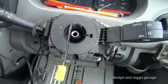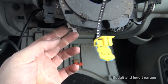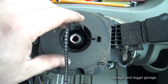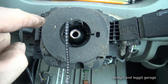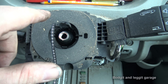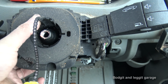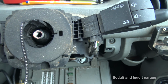Now, here is our clock spring, and on this one it's really handy, there's a lock. So you can actually wedge this up if you were to take it off, to stop it turning inside, because this has to turn inside, as you can see. And if you've got this set wrong, as you spin the wheel you can actually snap it inside. If it's turned too much to one side and then you turn it the other way, you can do damage, or you'll break it. So this is an actual lock under here, and as you can see now, it won't move. I release the lock and it moves. So it is very important to get that right.